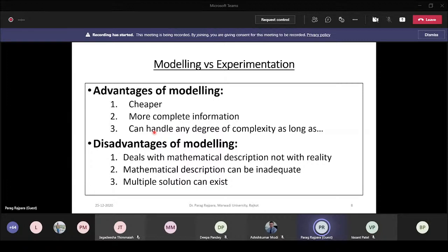Fine. So in simulations, whether you want to believe your simulations or not depends upon the level of input that you are giving. Level of input means the material properties, like thermophysical properties when you are solving fluid flow problems. If you give proper inputs, it will be good, and for proper data, you must have some reliable source.